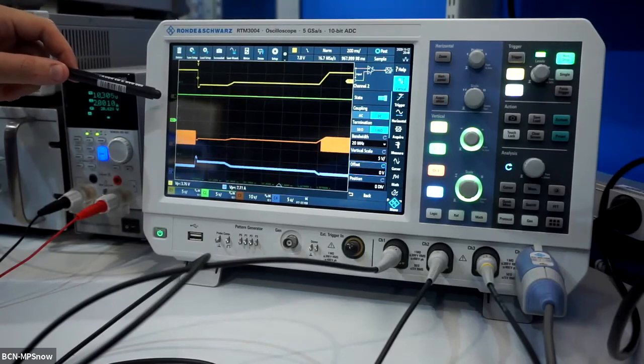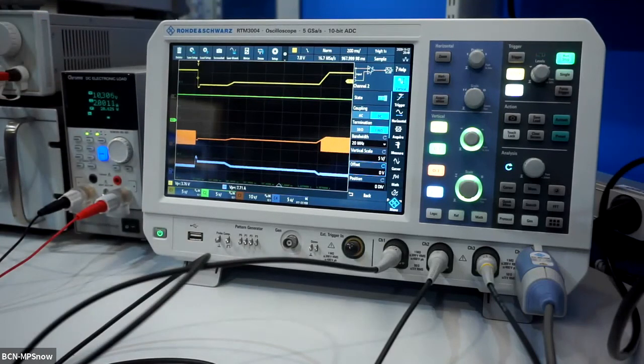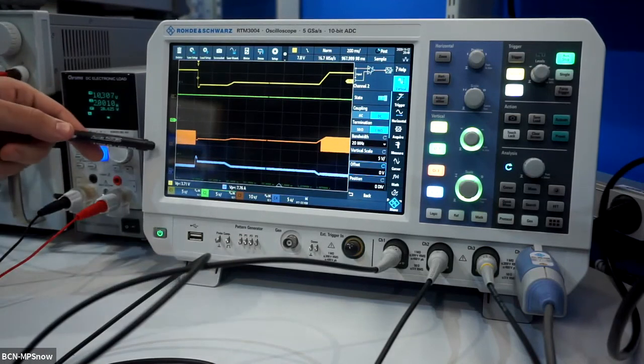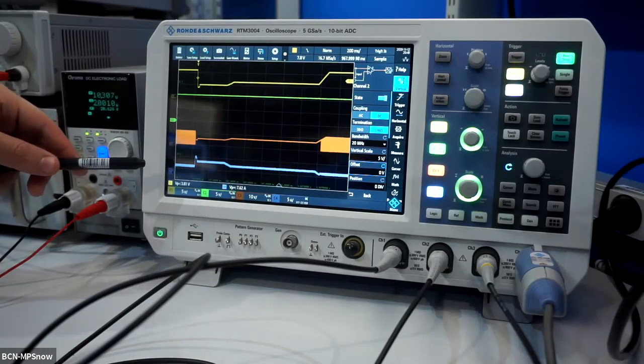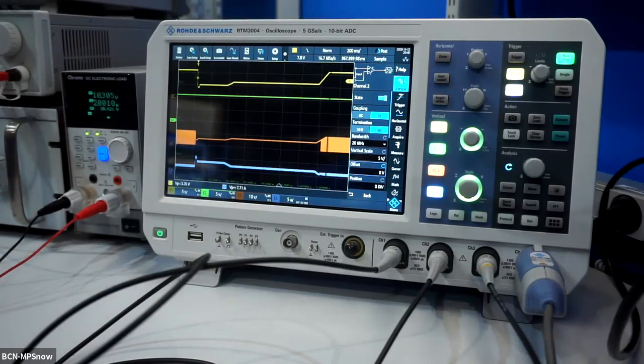As it can be seen, we have obtained a stable voltage, so the buck-boost converter is working as expected. In orange, here is shown the first switch node, and it shows how, when it's switching, the converter is working in buck mode. Finally, in blue, we have plotted the current that passes through the inductor.